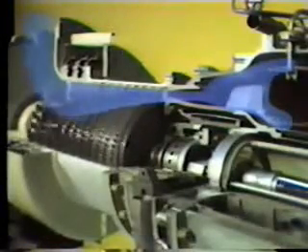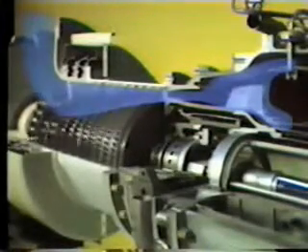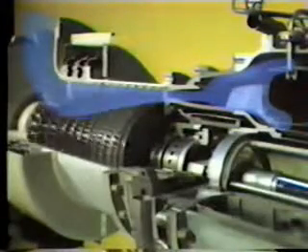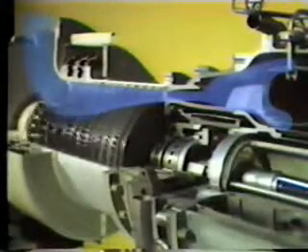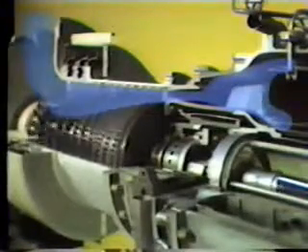The compression of the air plays an important role in producing power. The design of the compressor permits large quantities of air to be compressed into an exceedingly small volume, both to sustain and cool combustion. Diffusion, the key to compression, occurs throughout the compressor. The result is the delivery of high-pressure air to the combustor without any significant loss in airflow.